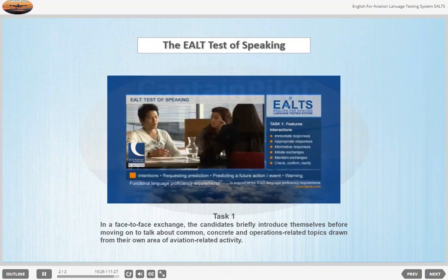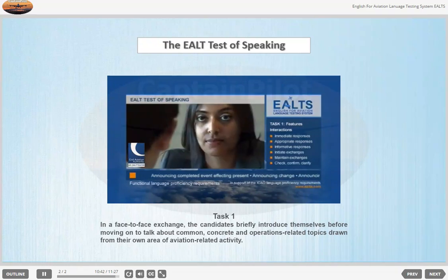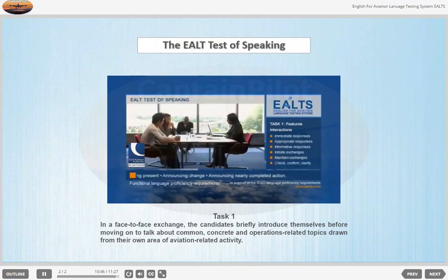Yeah, ECAM is the electronic centralized aircraft monitoring system. It's a system that has two flight warning computers that process data from the aircraft systems and give the pilot status information. ECAM monitors aircraft systems to give early notification of problems to the crew if anything is not normal.